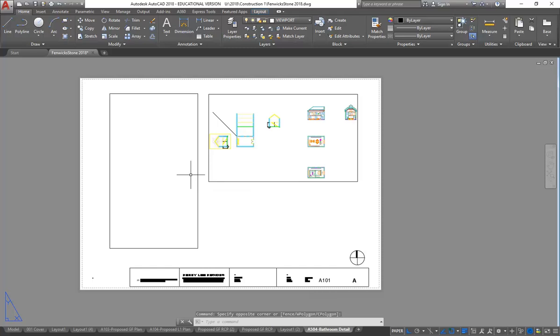Oh, it's more precise, so you don't have to go and work out the position exactly again. If you've already got the position right, and then you know that you moved your drawing 10 metres, it's much easier to just pan that amount exactly, rather than guess and then go back and draw the lines to line up exactly. So if you've got the way to set up, it'll make it a lot easier. And probably when you've done a few, it'll be a lot clearer why that pan option is really